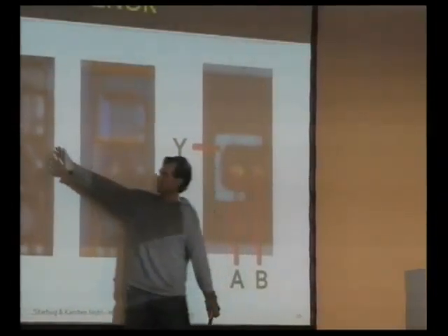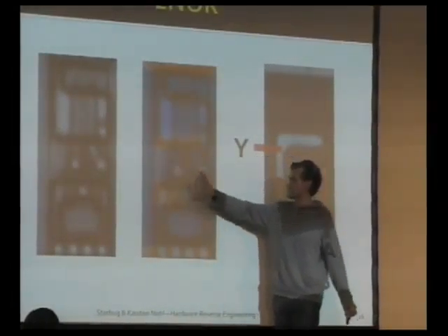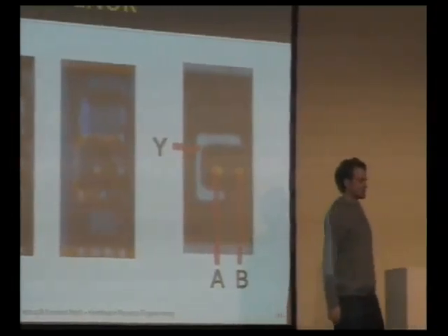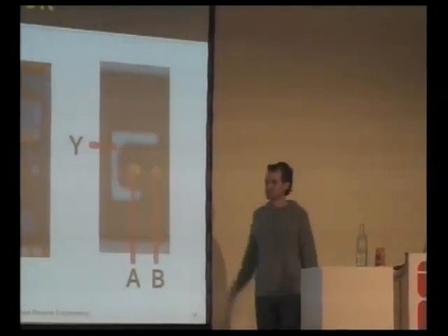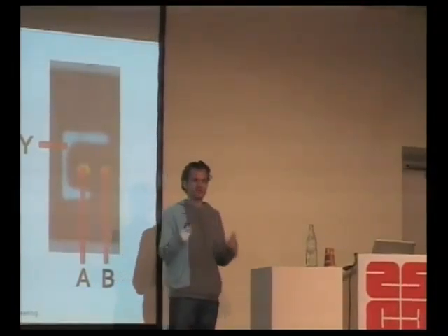This is one with four transistors, and if you look at how they're connected to each other, you'll see that the truth table gives you a 2-NOR function. And you do that for every gate.